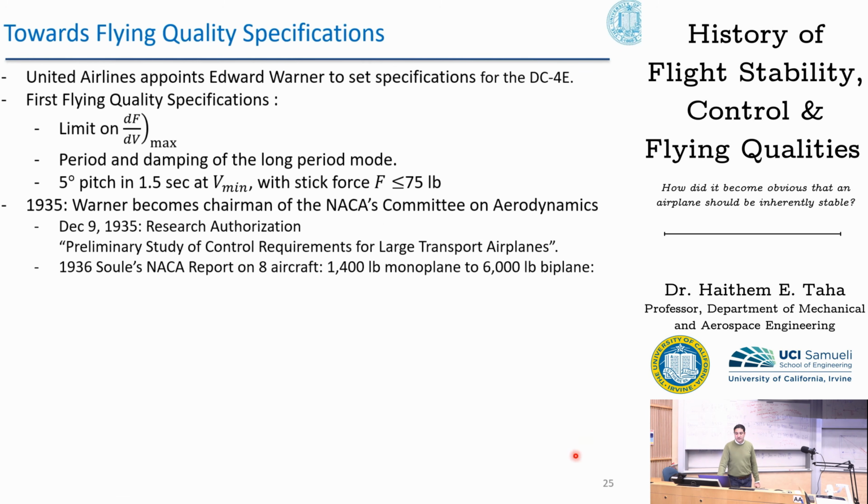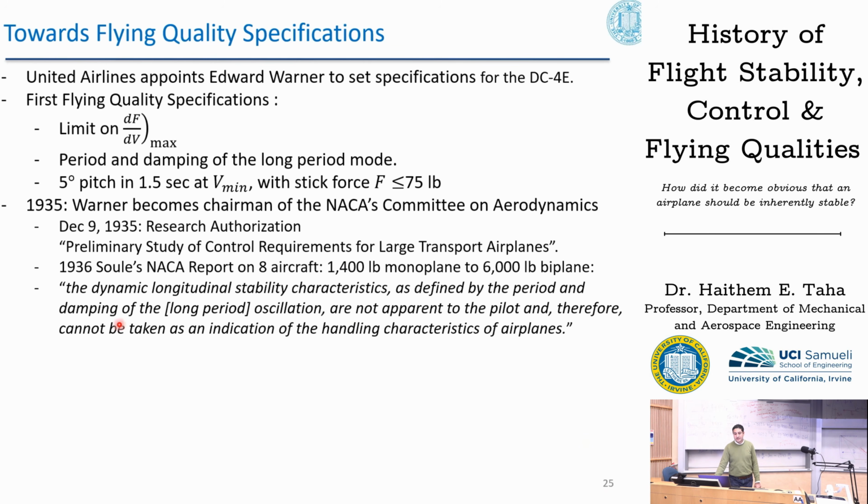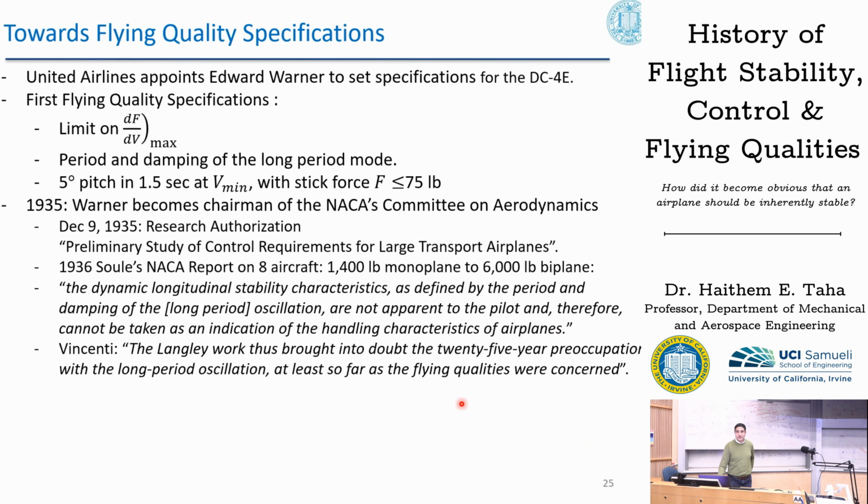One of the interesting outcomes from this work was that the dynamic longitudinal stability characteristics, as defined by the period and damping of the long period oscillation, are not apparent to the pilot and therefore cannot be taken as an indication of the handling characteristics of airplanes. This is what we discussed before, right? So they now discovered that the long period mode is of no concern. So Vincenti commented, the Langley work thus brought into doubt the 25-year preoccupation with the long period oscillation, at least so far as the flying qualities were concerned.